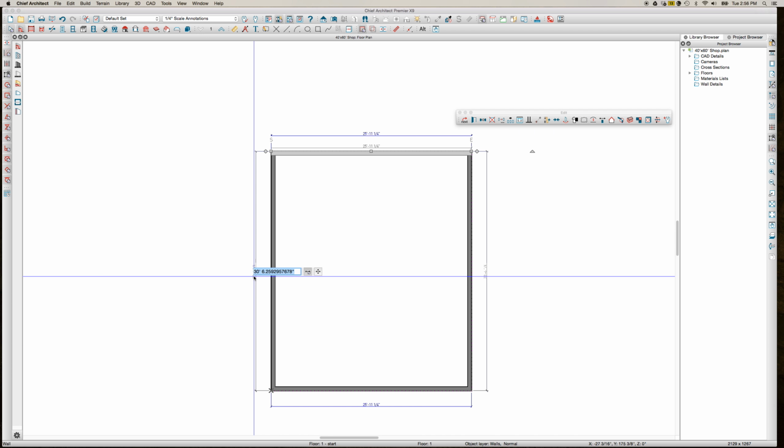So I'll go up here to my current floor, and in this dialog box I can set up the wall height that we're shooting for here. So we're going to go with a 12-foot wall. We always make it just an inch and an eighth taller. It works well with the studs. And that's a start for here. So here we have the main shop walls.